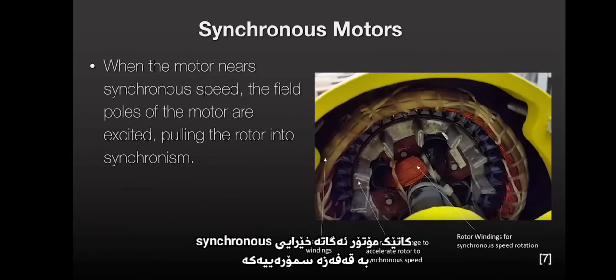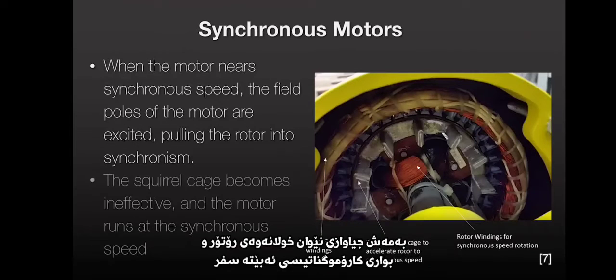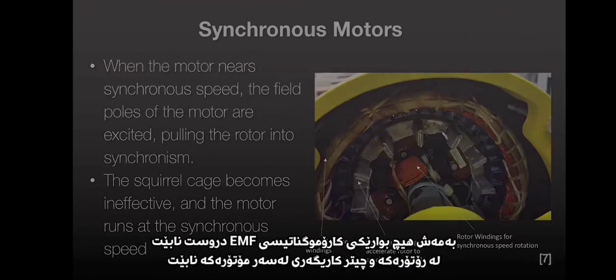Once the motor is accelerated to synchronous speed by the squirrel cage rotor, the copper rotor windings are given DC voltage, pulling the rotor into synchronization with the rotating stator magnetic field. The relative motion between the squirrel cage rotor and the rotating magnetic field is reduced to 0. There is no induced EMF in the squirrel cage rotor, and it no longer has any effect on the circuit.